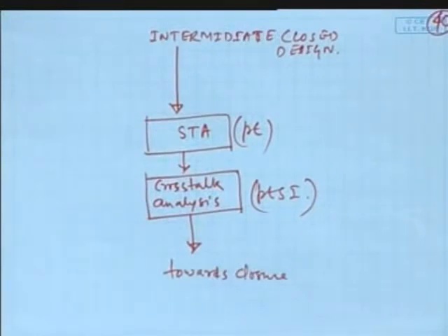Okay, I shall show you how. Synopsys provides, along with its own static timing analysis engine, which is called PT, Prime Time, a separately licensed tool called PTSI, Prime Time Signal Integrity. That tool is capable of doing this crosstalk analysis. Even Astro has some kind of crosstalk analysis capability. It has to. You cannot always go back to PT and do the crosstalk analysis.